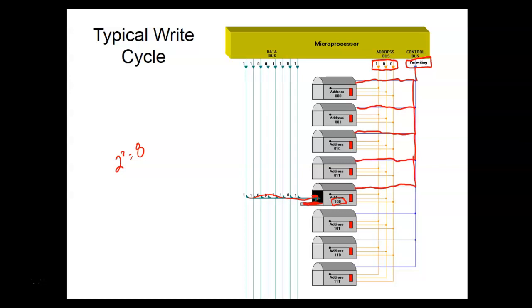You can't. One at a time. Yeah, only one of them is addressed at any one time. So it's just like your ports. Your ports are riding on this big old address bus, and we got this address decoder up here. And then we might have output 0, output 1, output 2, output 3, output 4, output 5. And I come over here, and if I put a 5 over here, then only that output would be active at any one time, right? That makes sense.